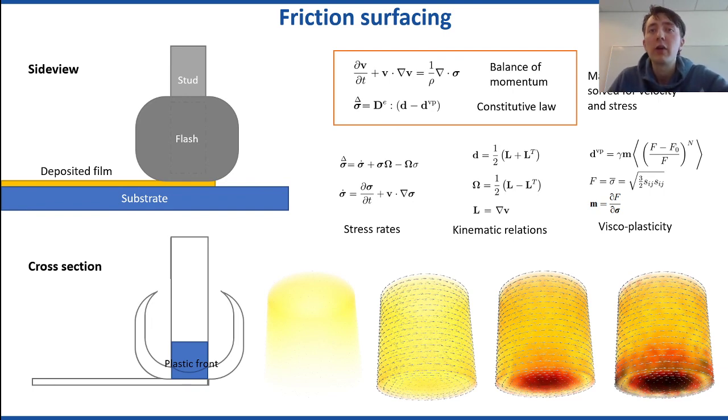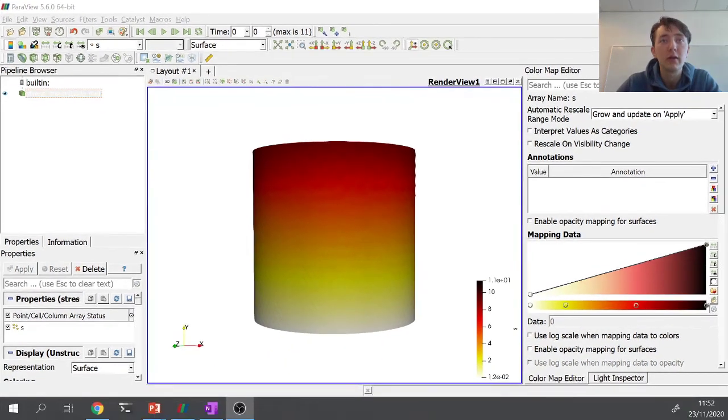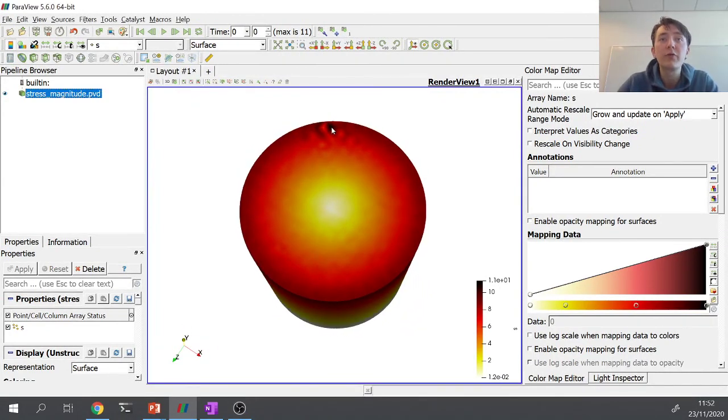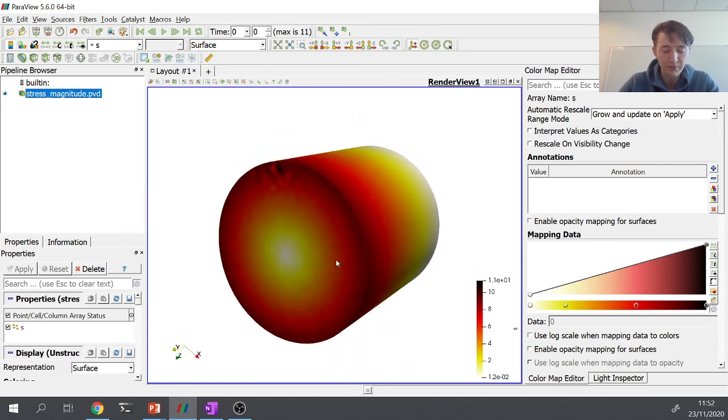Okay, so then I started mesh refining, and on this slightly finer mesh, I get a solution like that. Okay, that looks a bit smoother. But if I look a little bit more carefully, I found that I have some strange stress concentrations at some nodes in my mesh.